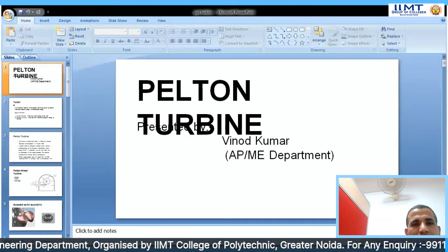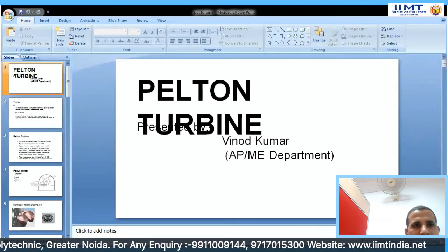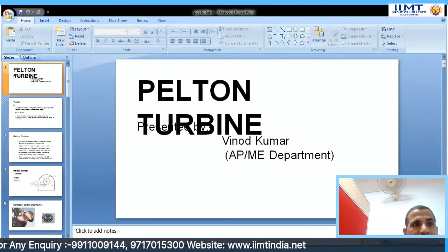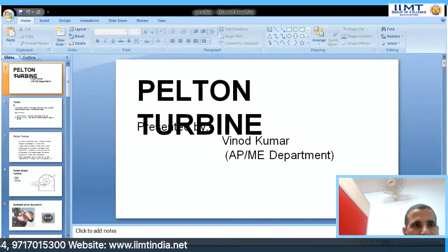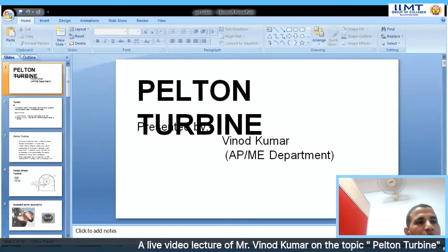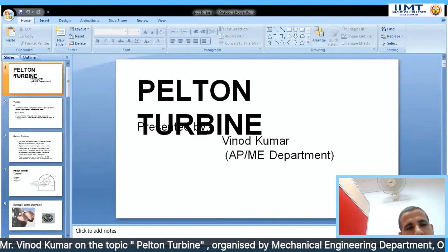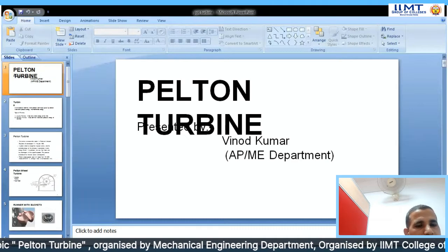The buckets have the splitter, and the function of the splitter is so that the energy of the water is not lost in between. Then comes the shaft. The shaft is the most important part of the turbine because this is the one through which we get the output of the turbine. And this shaft is further connected to the generator. We will get the electricity.